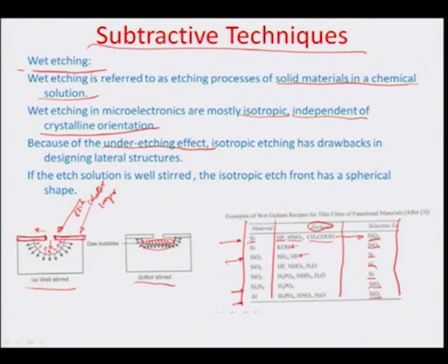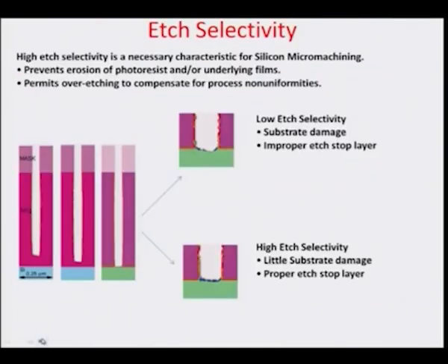So, that is all about wet etching. The selectivity can also be defined by the way that the etching performs while meeting this selective layer. For example, there are two illustrations here, case 1 and case 2. Here, for example, the etch selective layer, which is this yellow layer between the green and the pink, the etchant is not very selective. So, it has low etch selectivity.